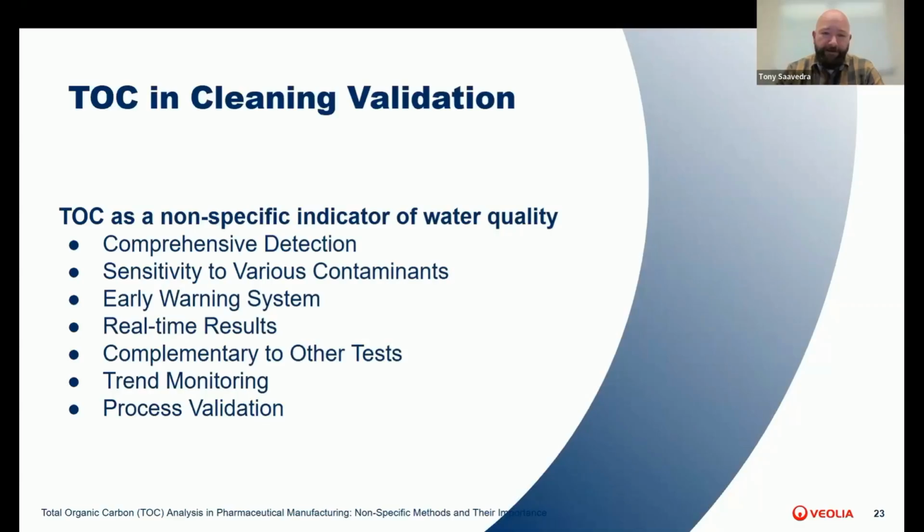And then process validation. TOC plays a crucial role in validating water purification processes. It can help demonstrate that your purification system is consistently producing water that meets the required quality standards. This is essential for regulatory compliance and ensuring that the safety and efficacy of pharmaceutical products is met.